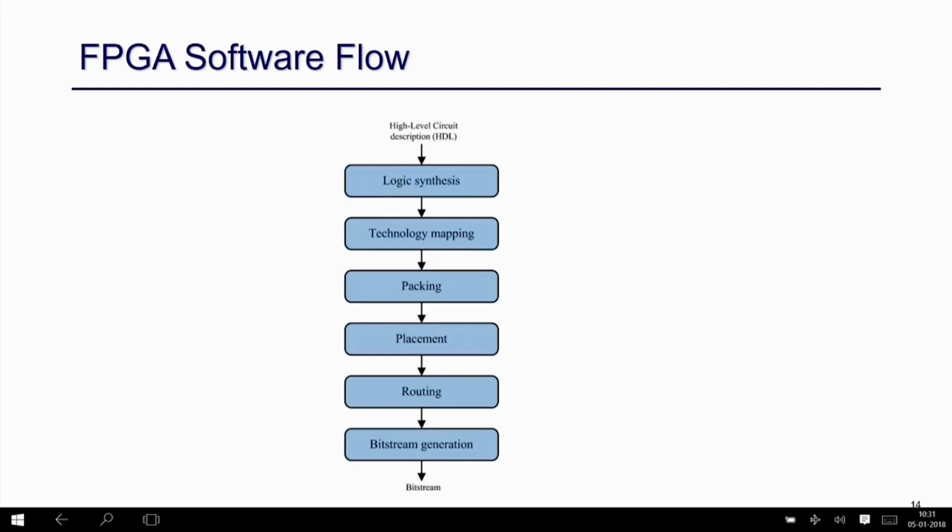So, in FPGA, after logic synthesis is done, you have to map your circuit into LUTs, DSPs and RAMs, because you do not have any gates in the FPGA board. So, whatever the circuit is, you have to find out how many gates are there. If you know your design has, say, k-input LUTs, so 4-input LUTs, you have to figure out all possible such 4-input patterns in your design, and that has to be mapped into a single LUT.